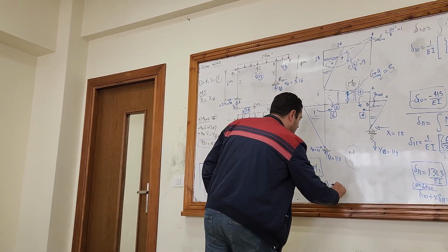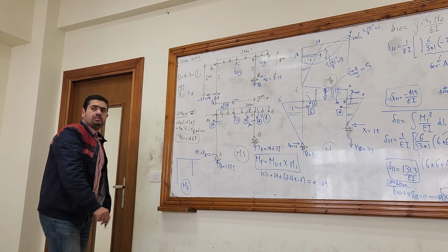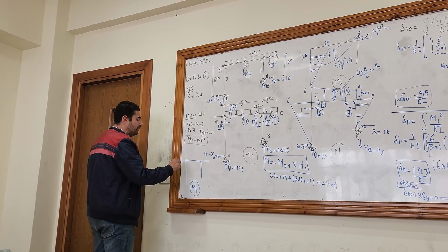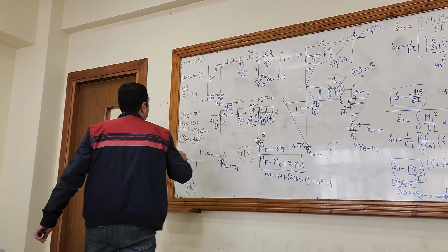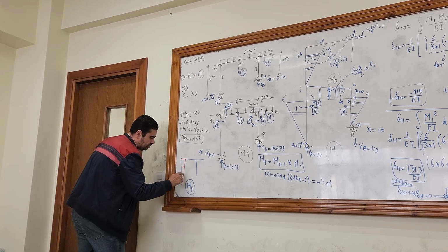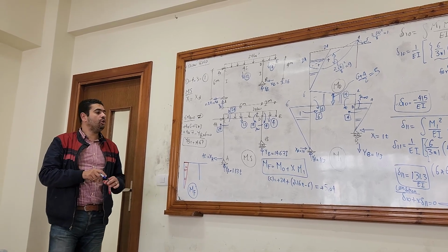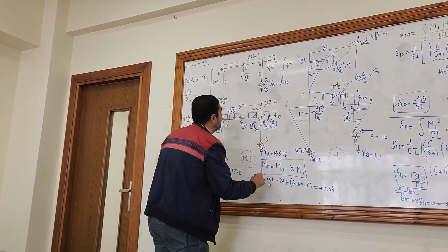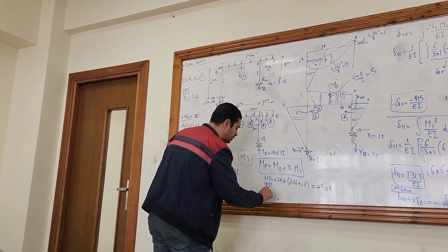So positive 5.04. So the moment at C is positive. What does positive mean? A positive moment is down. So the vertical member here, the moment will be 5.04, and here a straight line. Right? What about the other joint at D? Can I calculate only one time at D? Or it has to be 2 times, right? D, E, and then D, B.